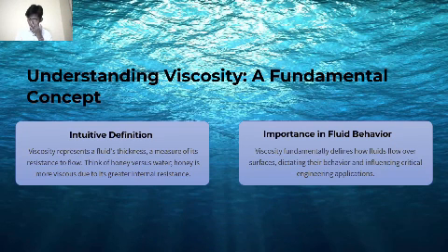Before jumping into Newton's law of viscosity, let's understand the concept of viscosity. Viscosity represents a fluid's thickness, that is a measure of its resistance to flow. It also defines how fluid flows over surfaces, dictating the behavior and influencing critical engineering applications. Let's think of honey and water. Honey has greater internal resistance, that's why it is more viscous.